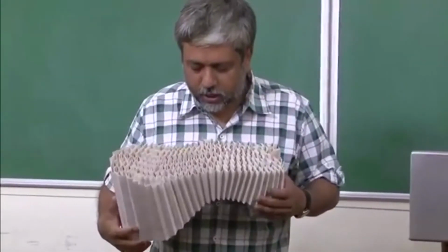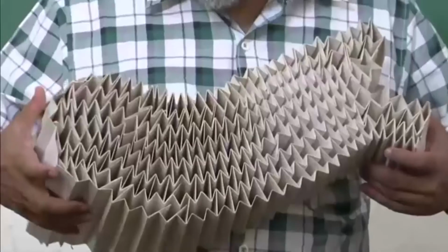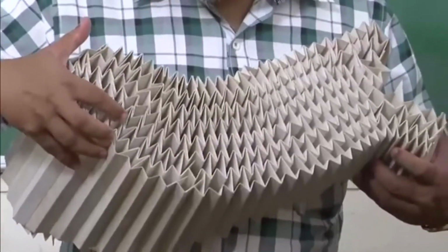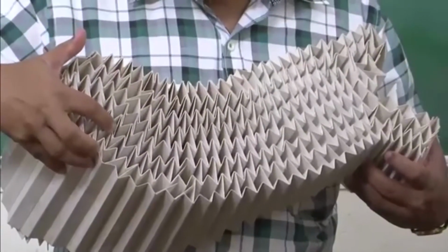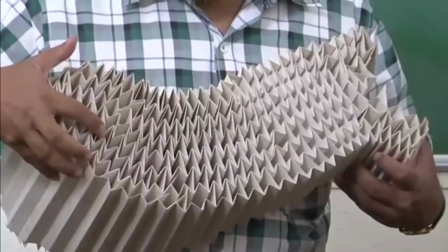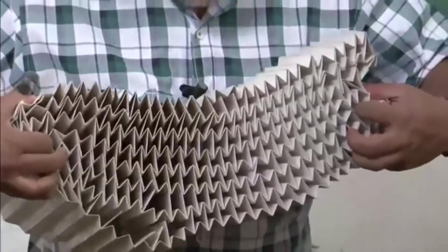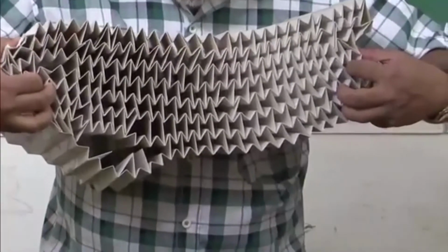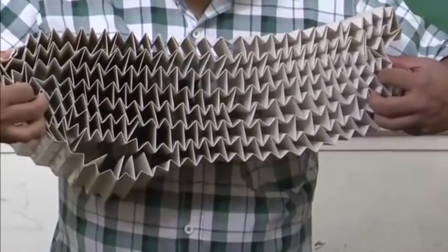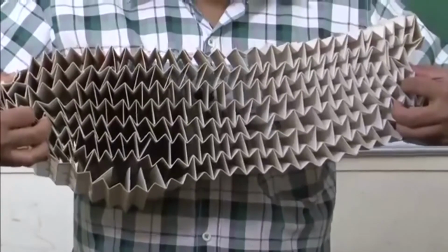Now, this is a kind of a re-entrant honeycomb structure. This is an auxetic structure. So, in this auxetic structure, if you look at it, each of the honeycombs, instead of a honeycomb with a positive angle, they are having a negative angle, each one of them. And what happens in such a case? Suppose now I am trying to expand the material. So, I am expanding it in this direction. You see that in the other direction, that is in the perpendicular direction, instead of contracting, it is actually expanding.